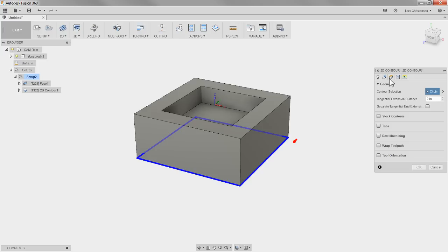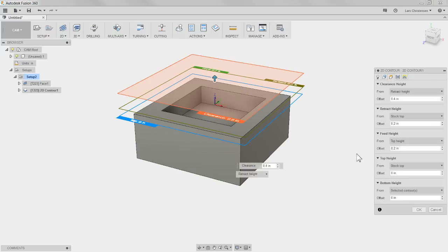And then I'm going to go over to the heights tab, and I just wanted to take 2 seconds to explain that heights tab because this can become a little bit confusing normally. Now, if you have done any of my tutorials before, I always talk about whenever you're working with a dialog box, start from the top and work your way down. Well, in the heights tab for CAM, I actually recommend you go the opposite way.